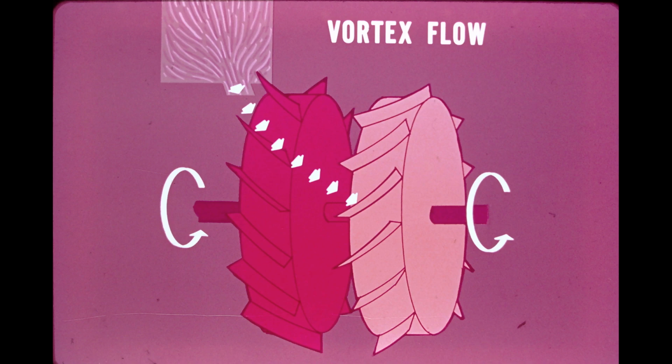And remember that water flowing from the water box has kinetic energy, or we might say has the capacity to do work. The water has already set the orange wheel in motion, but has not yet used all of its energy. Therefore, the water coming off the side of the orange wheel still has enough energy to do more work. We can use this energy by positioning a second wheel with blades curved to absorb the energy of the water and cause the second wheel to rotate in the same direction as the first.